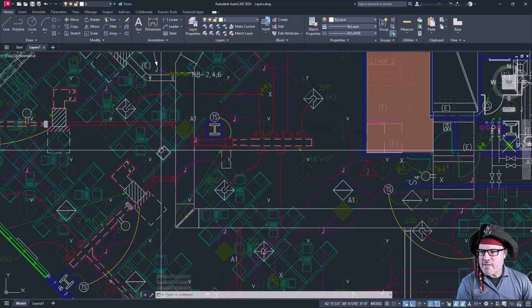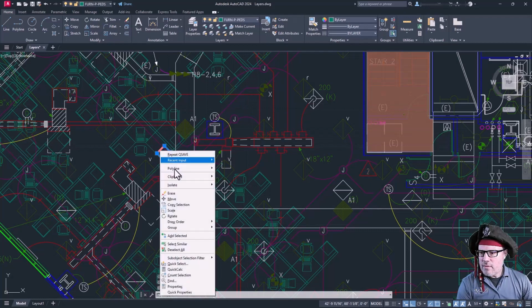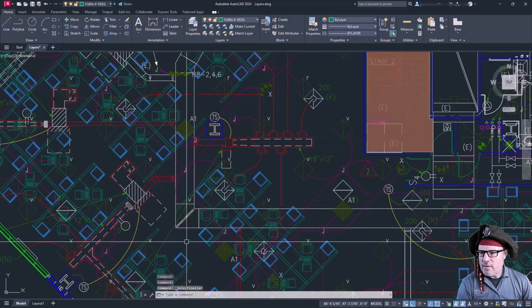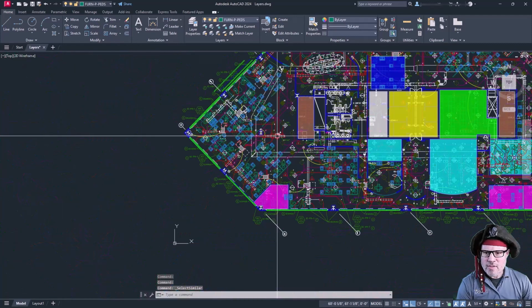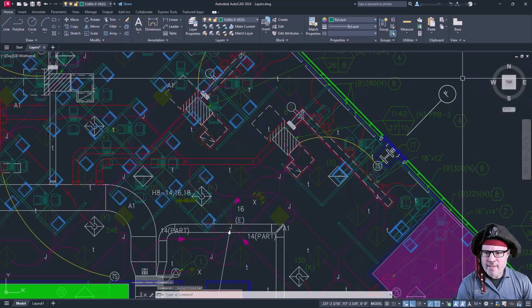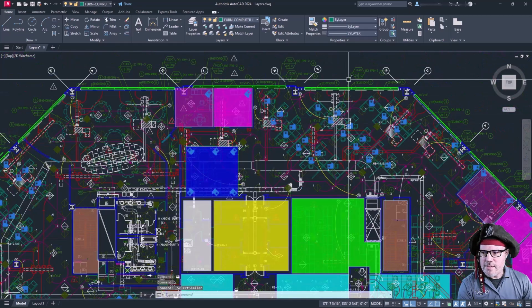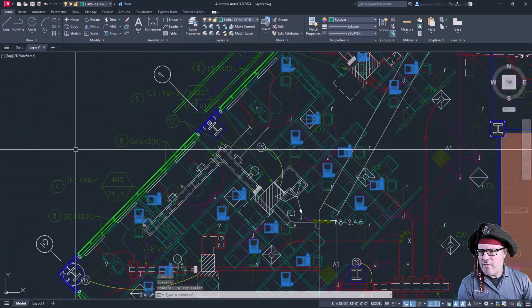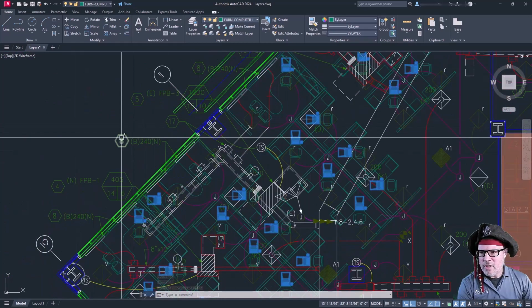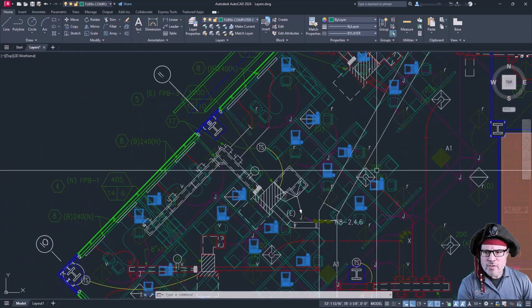Right-click on any existing object and choose Select Similar. We'll select all objects across the entire drawing of that type with similar properties, making it very easy to select groups of content of the same types, manipulating them all at once, or changing them to something different.